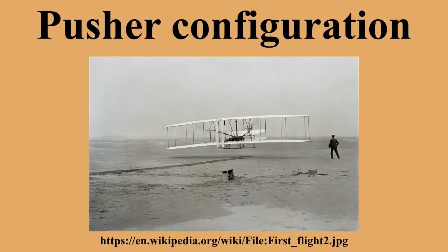Pusher props are noisy, and cabin noise may be higher than tractor equivalent. Propeller noise may increase because the engine exhaust flows through the props. This effect may be particularly pronounced when using turboprop engines due to the large volume of exhaust they produce.